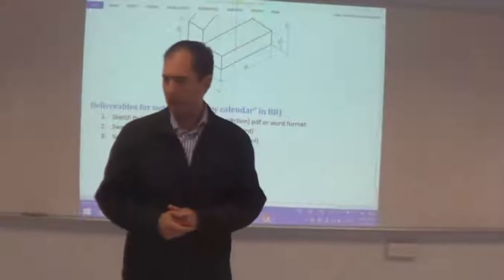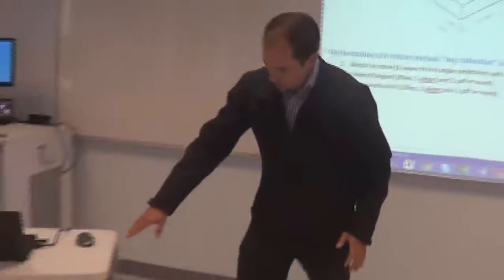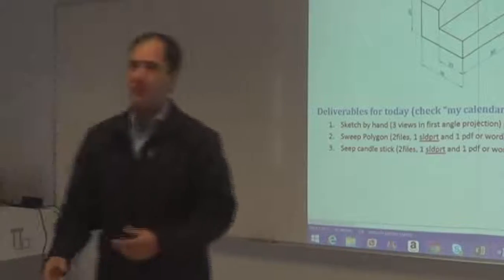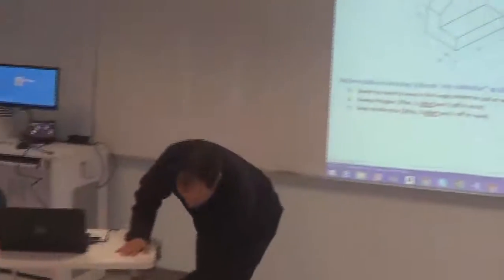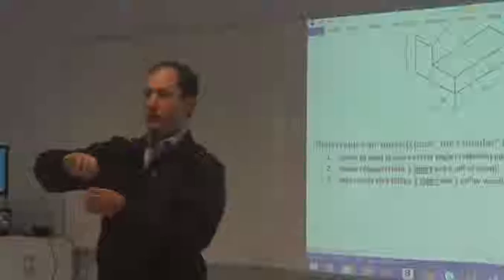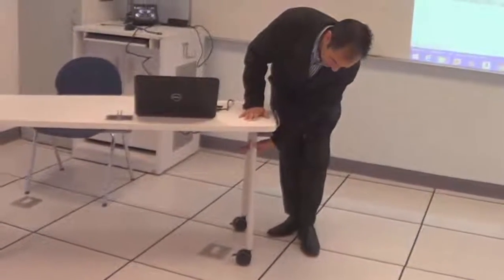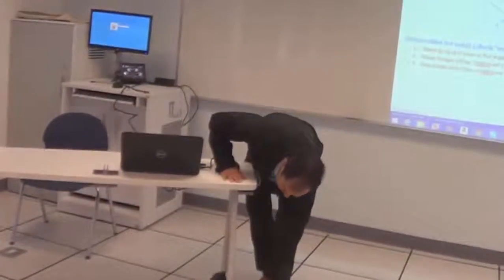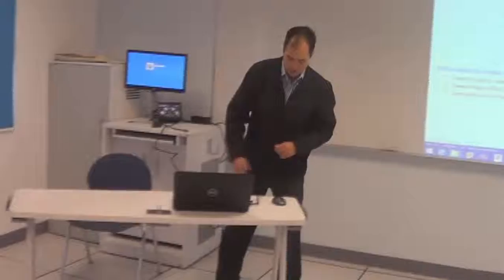Another example would be, let me see if I have something here in the classroom. This table, this kind of tube cannot be built with an extrude command, because the extrude command, remember, is straight, and we have some curve over here. So this curve requires specifying two sketches. The first sketch is a section, the circle of the geometry, and the second sketch is a path. Where is this circle going from? Okay? So let's check it out on SolidWorks.